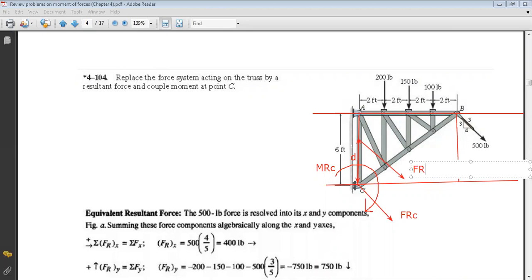Bravo. Yes, exactly. We will only take the component producing the moment, but you will displace the force as it is. But which component will produce the moment? The x component or the y component? The x component. So once you want to do your calculation here, when I displace my force on line AC, the y component will not produce any moment because it's passing by C. So the component that will do a moment about C is the x component.